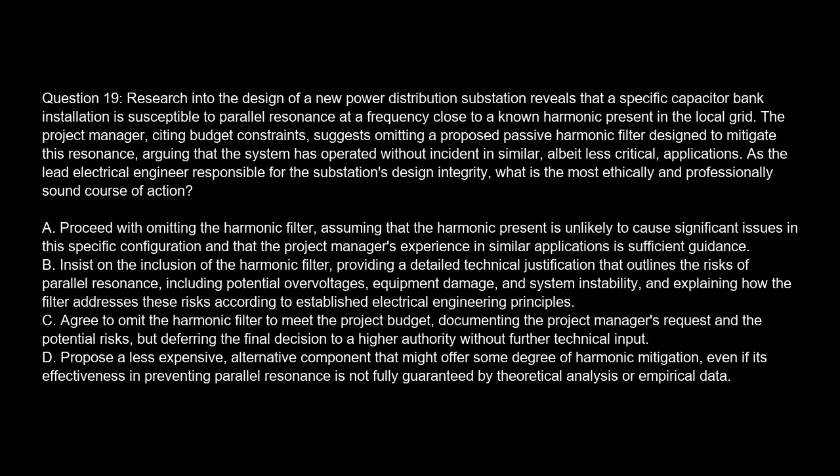Option A. Proceed with omitting the harmonic filter, assuming that the harmonic present is unlikely to cause significant issues in this specific configuration, and that the project manager's experience in similar applications is sufficient guidance. Option B. Insist on the inclusion of the harmonic filter, providing a detailed technical justification that outlines the risks of parallel resonance, including potential overvoltages, equipment damage, and system instability, and explaining how the filter addresses these risks according to established electrical engineering principles.